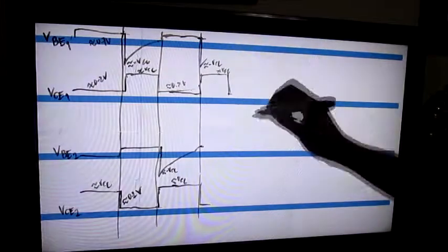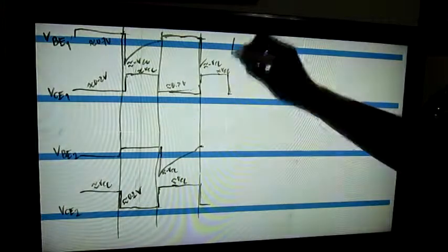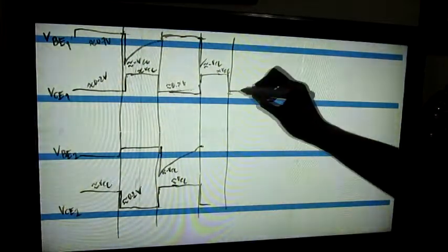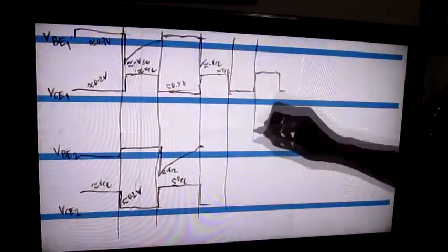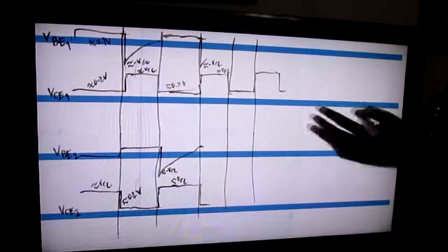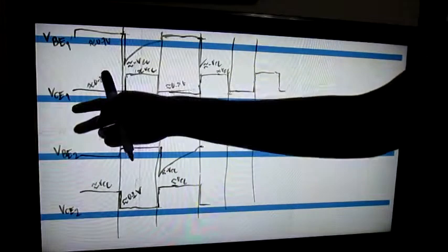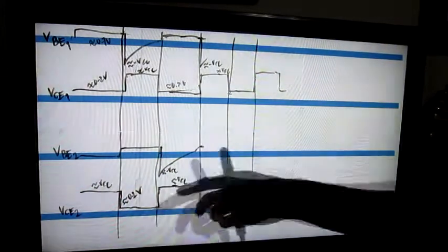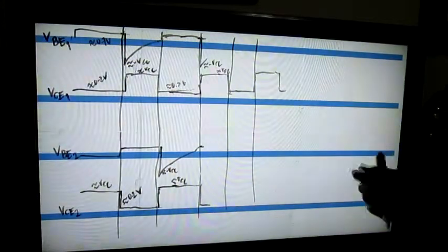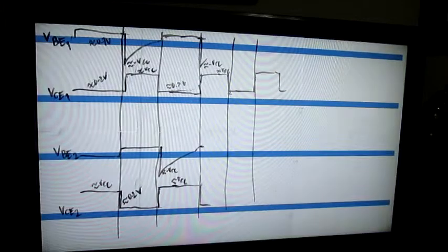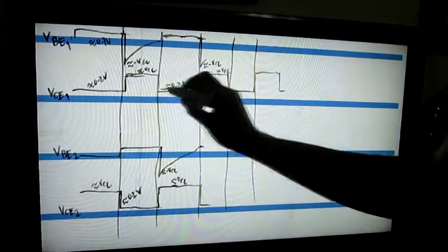Upon continuous simulation of the waveforms, we can see that the astable multivibrator produces almost square wave patterns. The output could be retrieved from either the collector emitter of Q1 or the collector emitter of Q2. This shows that the astable multivibrator is a square wave generator, and to add, these states are the quasi-stable states.